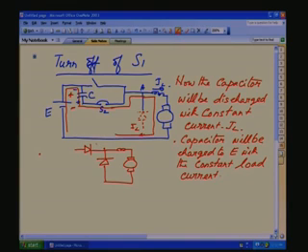The diode is switched off, this is S1 here, and the capacitor is charged in the opposite direction to E. Then you have the E here, this is E, this is also E. So, this is the circuit, it is ready. The capacitor is charged, and again when S1 is turned on, through resonance charging it will charge in the opposite direction and it is ready for commutation.